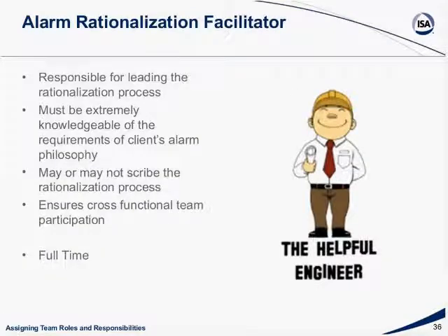Now you're going to have your alarm rationalization facilitator, and this is a very key position. This person is responsible for leading the rationalization process. They have to be extremely knowledgeable of the client's alarm philosophy. Right? When I say client, this person needs to be from outside the company, and I'll talk about that here in a minute, okay? But this person is going to lead the rationalization process as you're going through, and you're going to ensure cross-functional team participation.